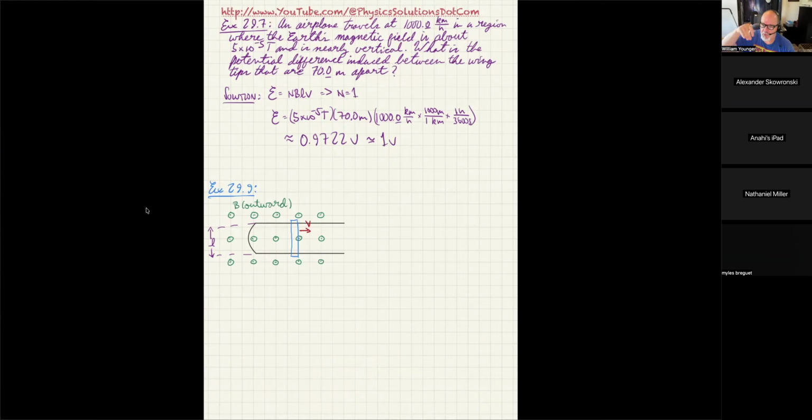So if we imagine taking our right hand and poking our fingers right in the middle of that hole between the blue bar and the curved black bar, then that is the direction of the magnetic field. Now, if I take my palm and wrap it around that bottom wire, I'll see that my thumb points to the right, and that dictates that our induced current will actually be in the counterclockwise, or excuse me, in the clockwise direction like this, and that means also like that. So that's the direction of the conventional current. It's going in a clockwise fashion.